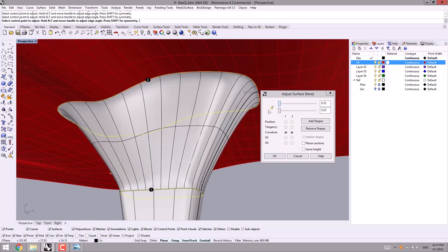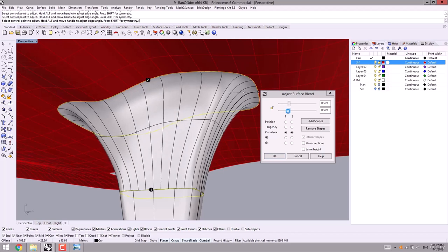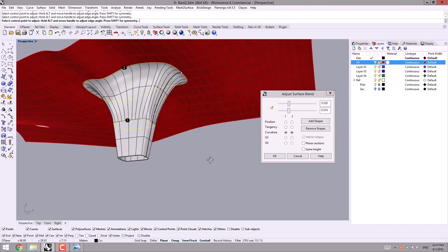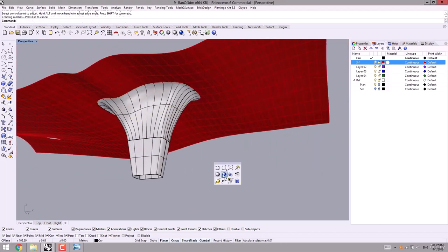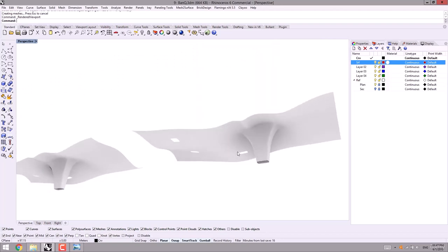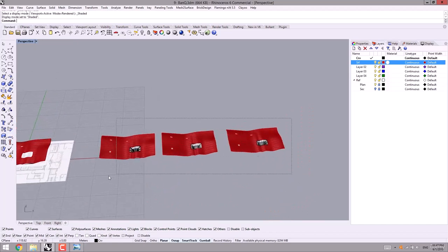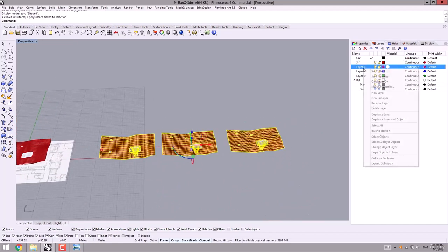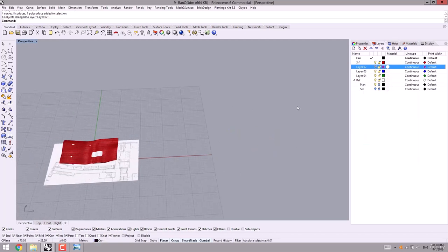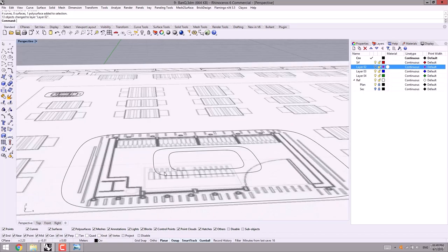first and end, as you can see. For example, I adjust them like this. Check it out. Following that, I click on OK to save the changes. Check it out at the render viewport. And as you can see, we could have modeled it even by using blend surface successfully. Then I select all of these and change the object layer and turn them off so that you can have them for your practice.